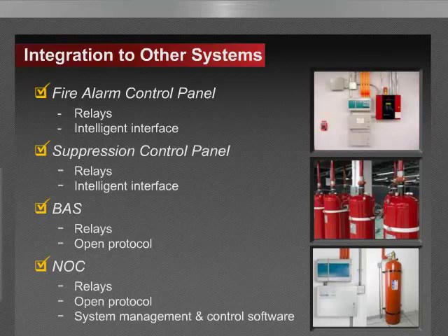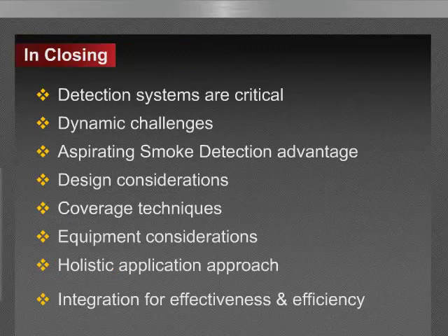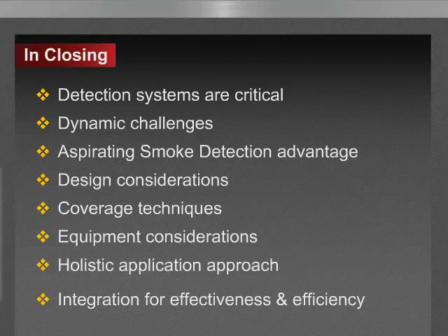So, in closing, fire detection systems play an essential role in the overall fire protection strategy and are critical for mitigating risks. Dynamic environmental and operational characteristics of IT communication facilities have resulted in a shift towards performance-based approaches, applying detection-specific environmental and operational conditions to meet particular facility requirements and owner objectives. Aspirating detection systems are well suited in meeting performance objectives of modern IT and communication facilities with proven applications worldwide.